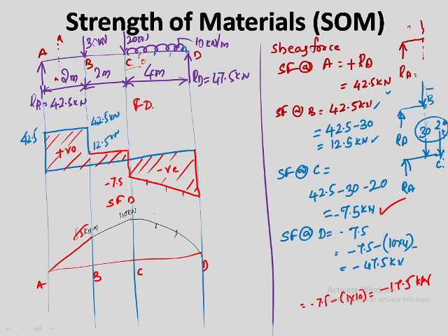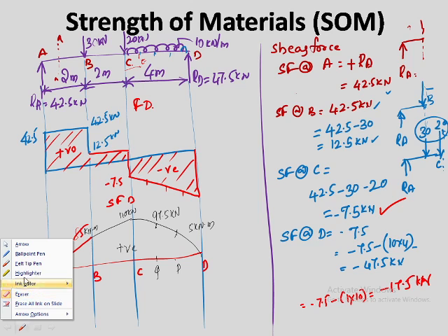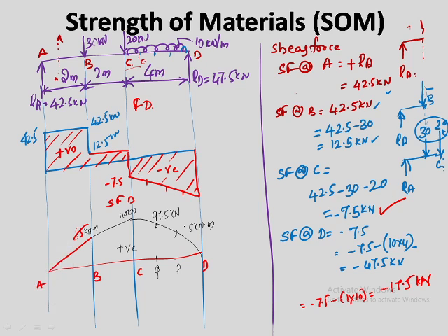Now you got 2 additional points here. So that is what a Q point and a P point. Q point you got 97.5 kilonewton meter, and this point you got 95 kilonewton meter. Now the bending moment is 75 here. This point is 75, P point is 75. Now this bending moment is positive.